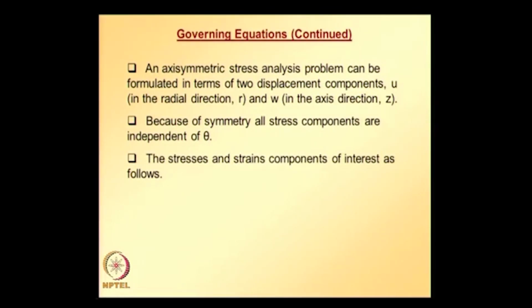The stress and strain components of interest are as follows: sigma r, sigma z, sigma theta, tau r z, and the corresponding strain components are epsilon r, epsilon z, epsilon theta, gamma r z. Assuming small displacements and strains, the strain displacement relations.